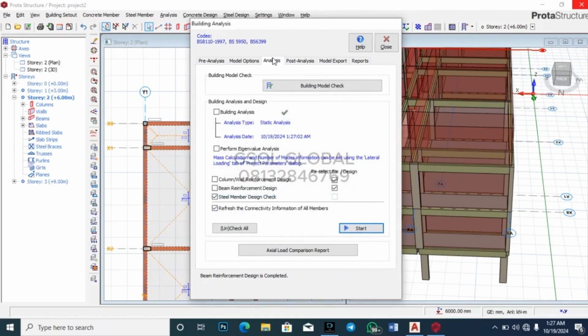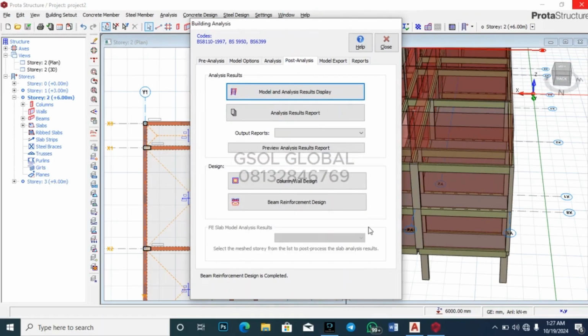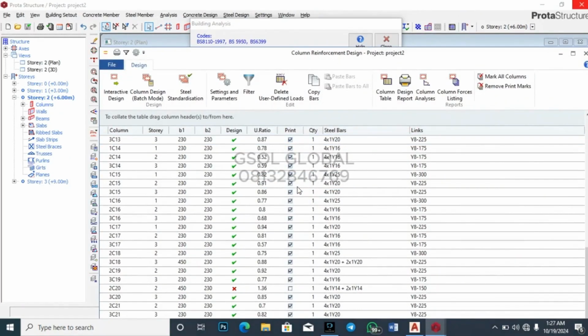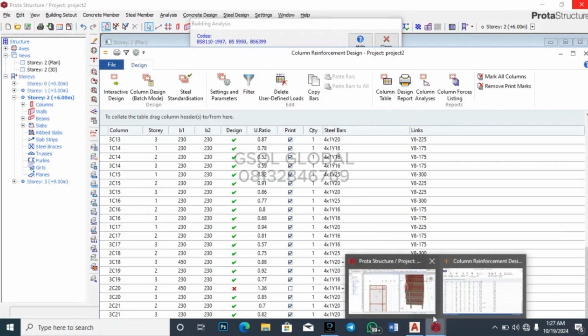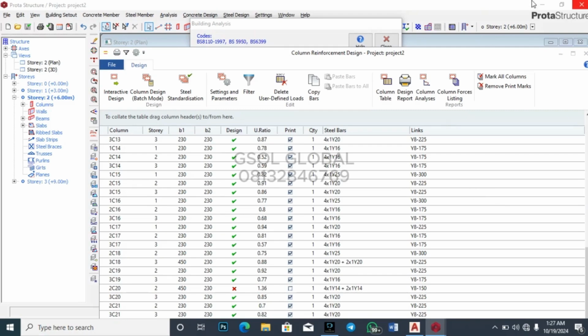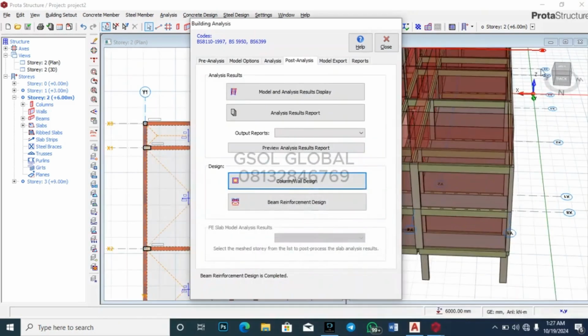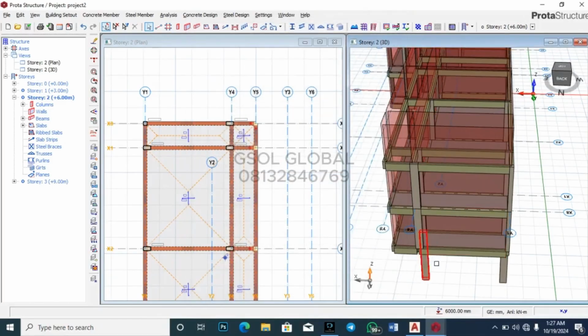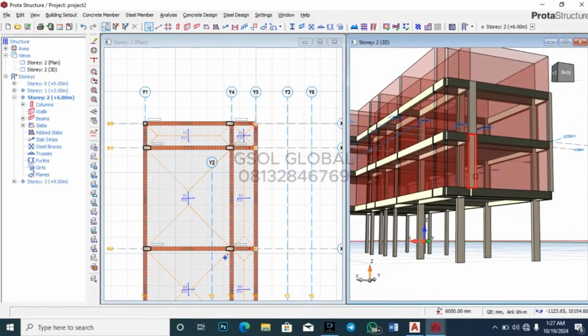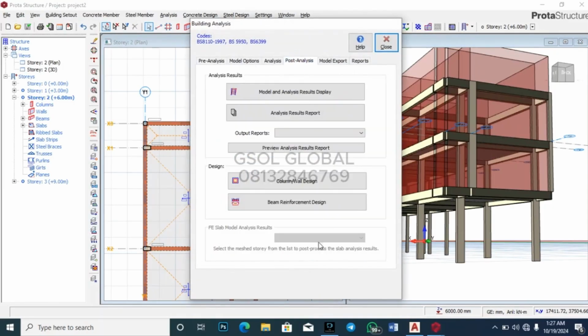Okay, so let's go and check now. I don't want any failing column. If we did not check that, we wouldn't know that this thing is still failing. You see it, right? So I had to just check. Okay, what happened? What changed? You see it, right? So let's close this. That 2C20 is still failing, so we have to go back and do our editing very well and get it right.